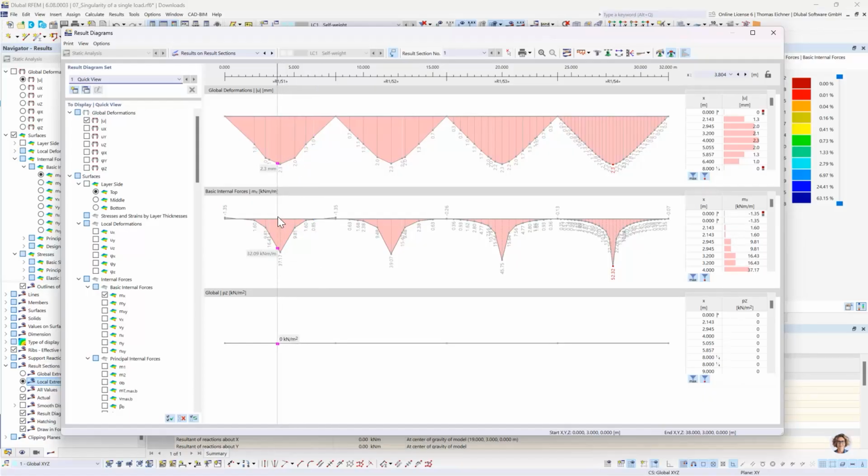Also, if we have a point force somewhere, in reality it won't be a point force. It won't be a needle where some force is going downwards. Mostly it will be like a column of dimensions 0.5 meters times 0.5 meters.